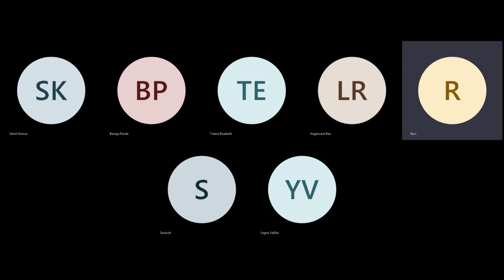So how many D pins, how many control pins, these are all inputs to your memories. They may be unique, or they can be different also. So you have to compute. That's where you will have to look at the fly line matrix. If all the fly lines are connected, means this pin is connected everywhere. That's when you will have to compute it as one net. Otherwise, you should compute it as multiple nets, as many nets as are possible. You understood? Outputs will always be different.